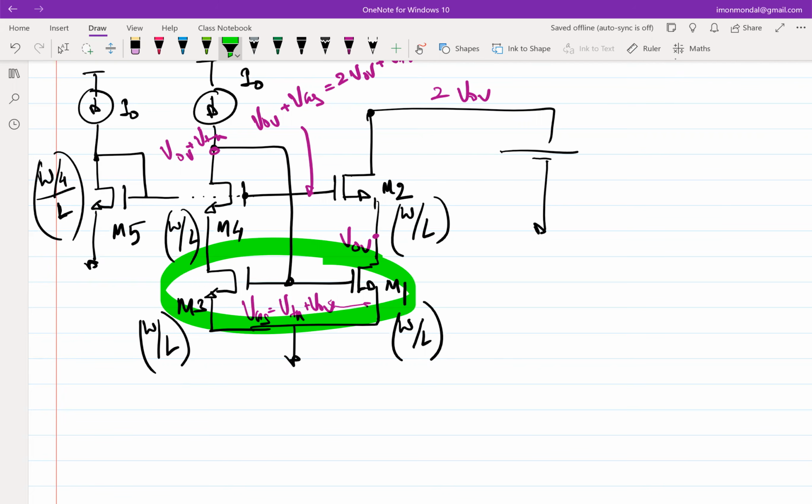So if you have to draw an equivalence between the current through M1 and M3, then you have to be aware not only that it is determined by the VGS, but also that there can be some difference due to VDS. So then you take into account channel length modulation of M3 and M4 and see whether that second order of accuracy is applicable or not. To the first order, let's say you are not bothered about whether the current is accurate within 1% or 2%, it's okay if it varies, then you neglect it. But if you have been asked to exactly match, then you cannot. So that's the whole premise of it.